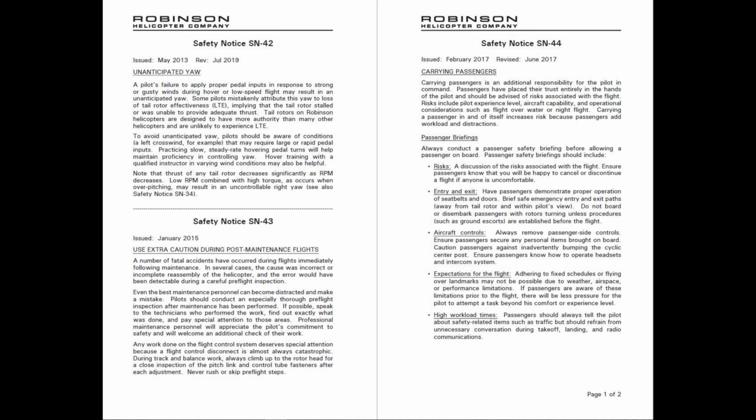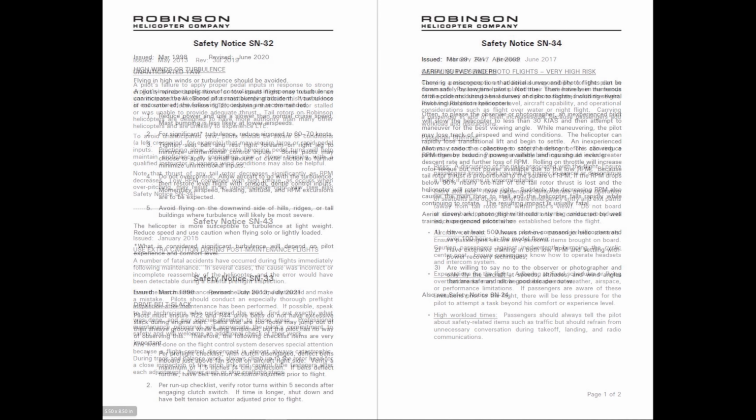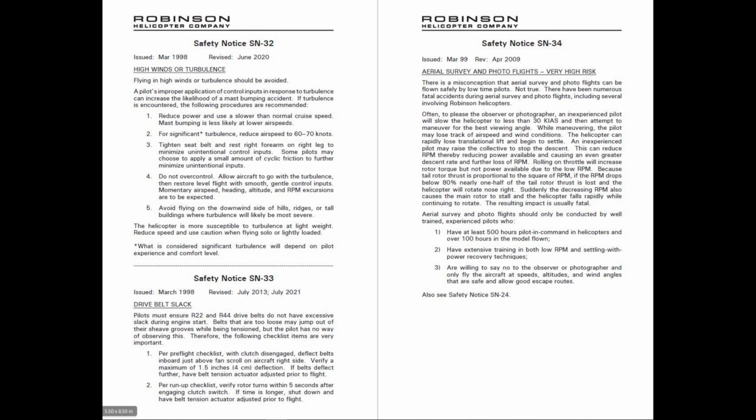If the belts seem to be tight, the pilot might want to leave the belts tensioned after the flight. Then after the battery switch is shut off, disengage the clutch. This will allow the belts to loosen slightly. Before the next flight, disengage the clutch to release tension on the belts before starting the engine.